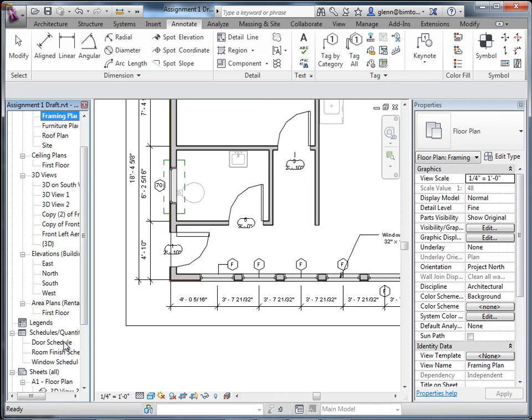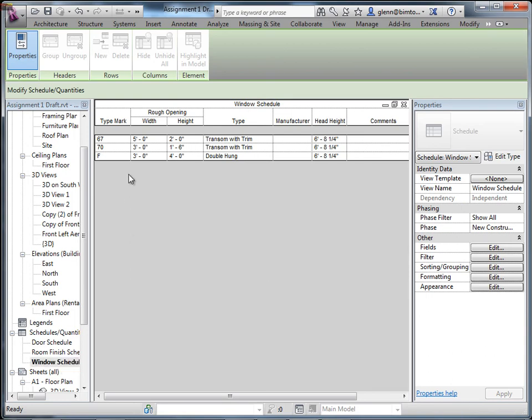And in this one, we've already created a door and window schedule. I think there's already a door and window schedule set up in your template. But if you go to the window schedule, you'll see that type window F is 3x4, a double hung, and that's information that we can use to then place it on the plan. So anytime anyone sees F, they know that I can look in the schedule and see what the actual specification is. I know that that's going to be a mill guard window.